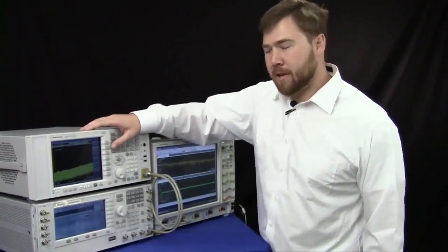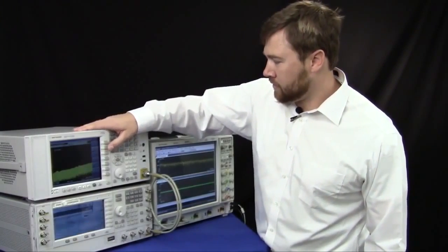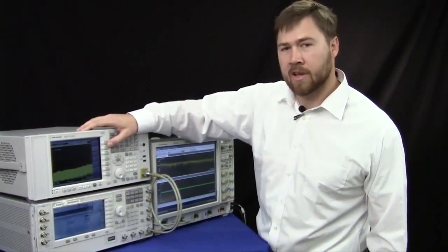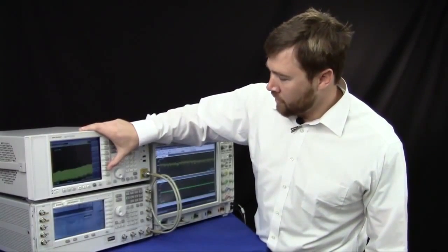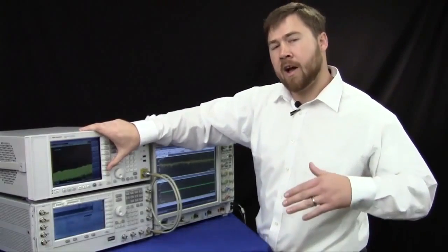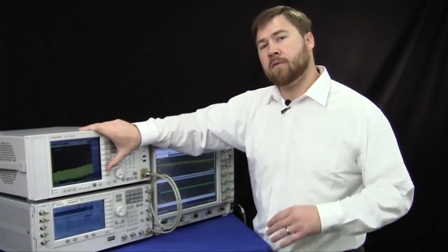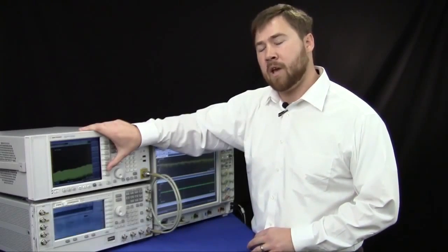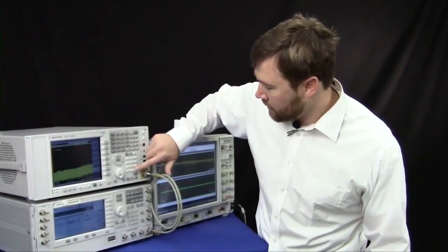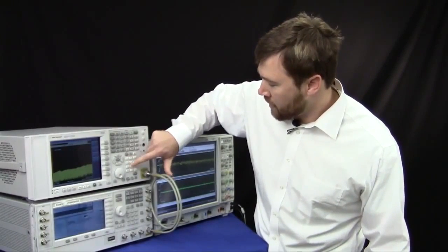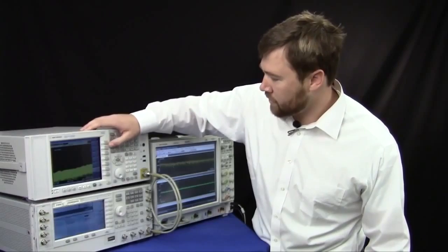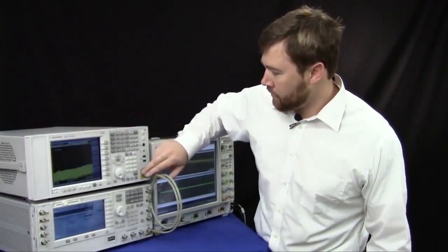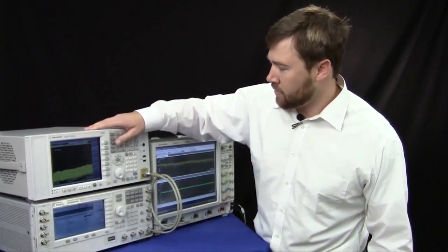Let's first set up our PXA. For this, I'm going to tune to the center frequency that I wish to analyze. So in this case, X band. Then I'm going to shift my IF higher from the normal 322.5 megahertz IF all the way up to 700 megahertz to take advantage of the full IF bandwidth. I'm going to do this by creating a negative frequency offset of minus 377.5 megahertz. So now I've shifted my IF up to 700 megahertz. Then I'm going to come back over here and reset my center frequency to X band.